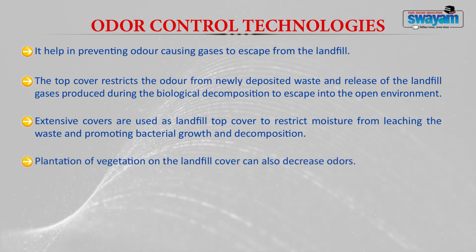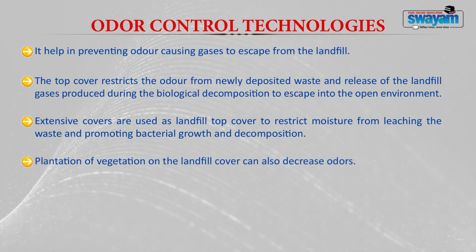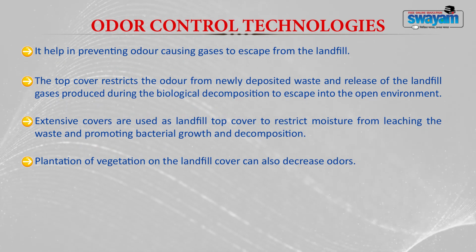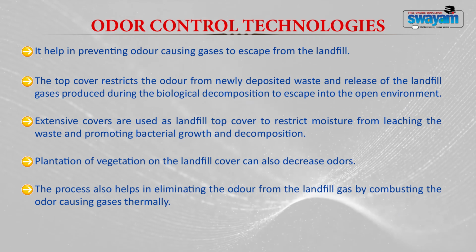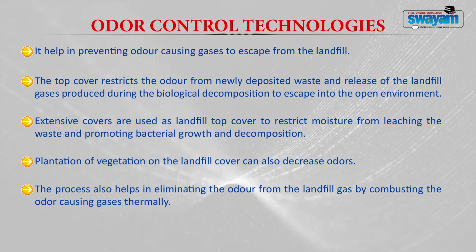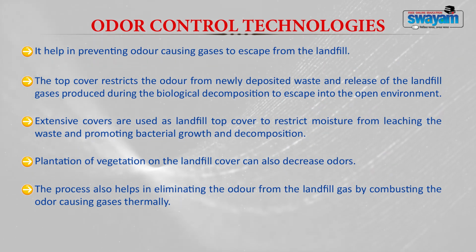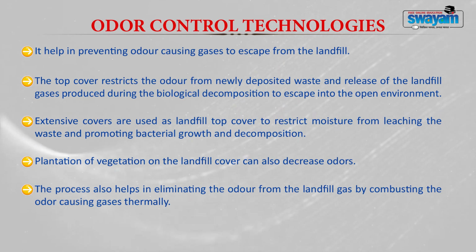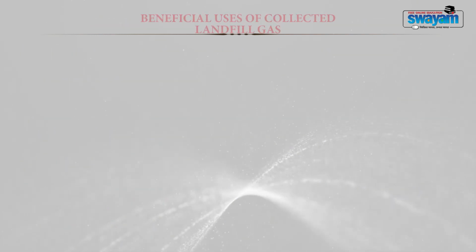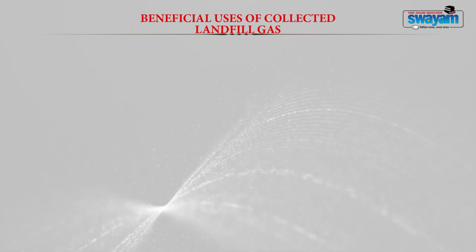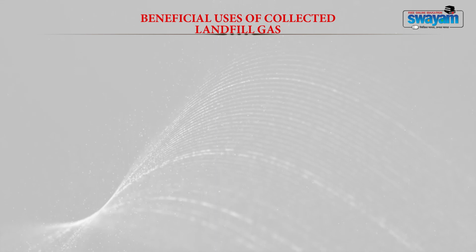Also, you can plant some vegetation on the cover which will also decrease the odor. The process generally helps in eliminating the odor from the landfill gas by combusting the odor causing gases thermally. Venting of landfill gas with the help of a filter can also decrease the odor that is generated during landfill gas generation. Now, lastly, let us discuss the benefits of the landfill gas.